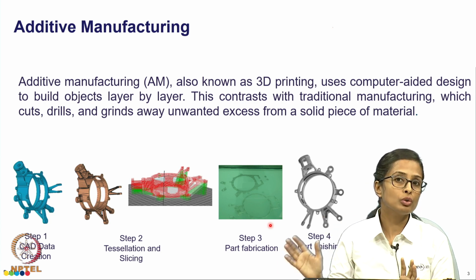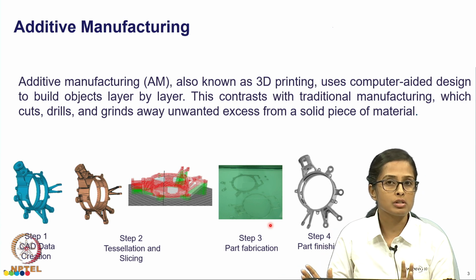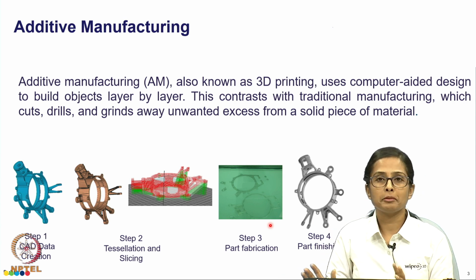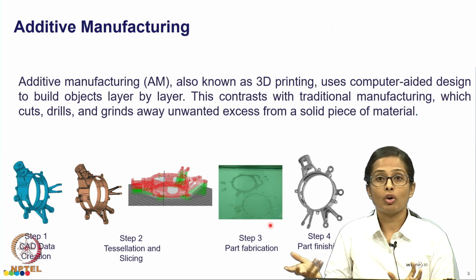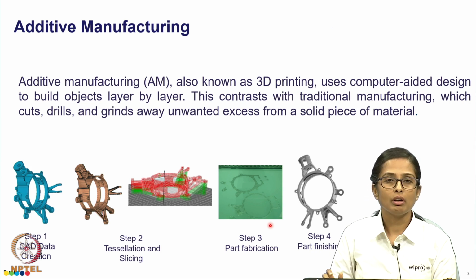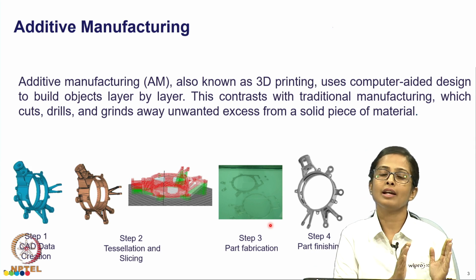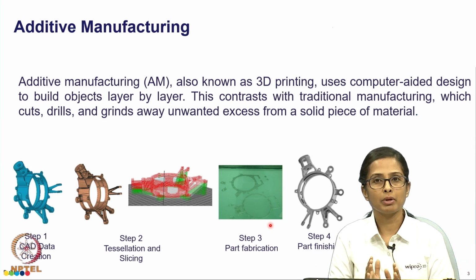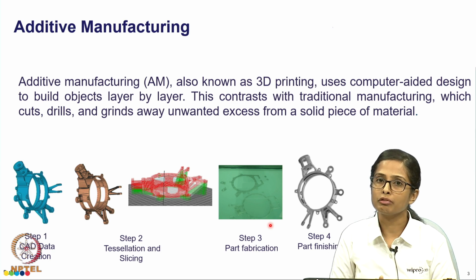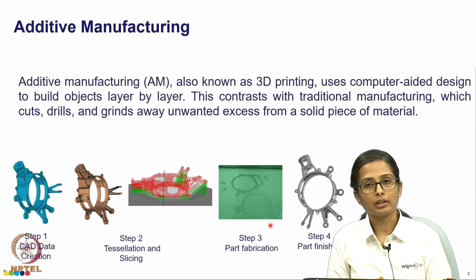So, you can put it through heat treatment cycles to improve its property, you can put it through machining process to get a more accurate part or a less accurate part, or a smooth finished part. You can also do polishing. If you need some kind of a coating, you can do that also. So, it is a near net shape that you get after 3D printing, and there will be some amount of post processing to get the final component, right.